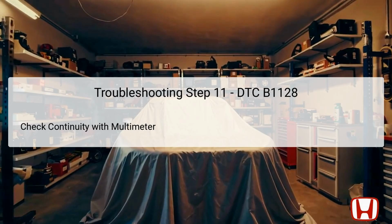If continuity is present, it indicates a grounding issue within the circuit, necessitating repairs to rectify any shorts present. However, if no continuity exists, this may suggest a faulty multiplex integrated control unit, MICU, compelling you to replace the under-dash fuse relay box. Understanding these conditions is integral for effective troubleshooting.